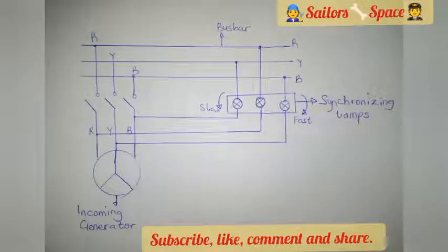So before we answer the question, we'd like to know what a synchroscope does. A synchroscope is a device on an electrical switchboard that shows the correct moment in which an incoming generator will be paralleled or synchronized with the running generator so that they can both share load and provide adequate supply of electricity to the entire system.